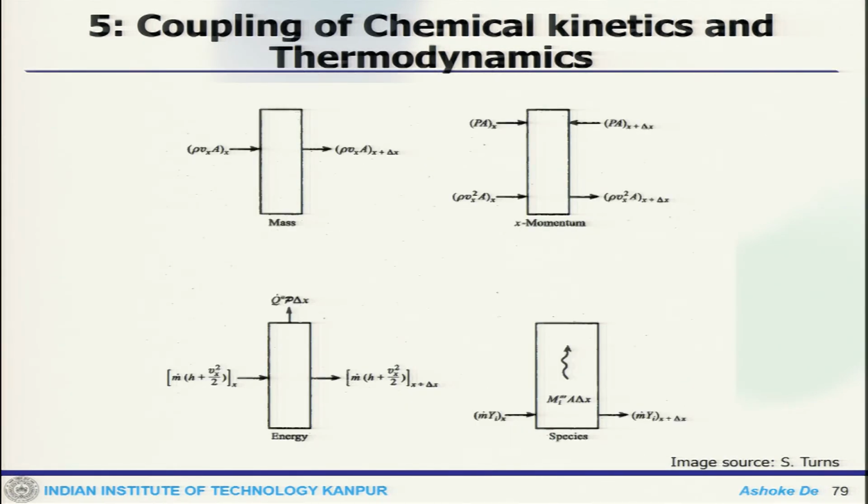Now we write down the mass conservation. That is the control volume. Whatever comes in goes out; this is x and this is x plus delta x, so that strip is a small infinitesimal element of width delta x. That is mass conservation, then there will be momentum conservation, and then energy conservation, with this much energy coming in and this going out, and if heat transfer takes place.